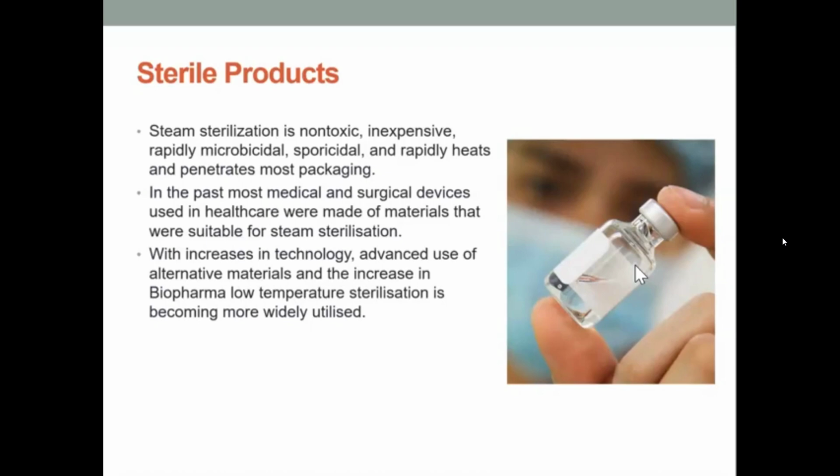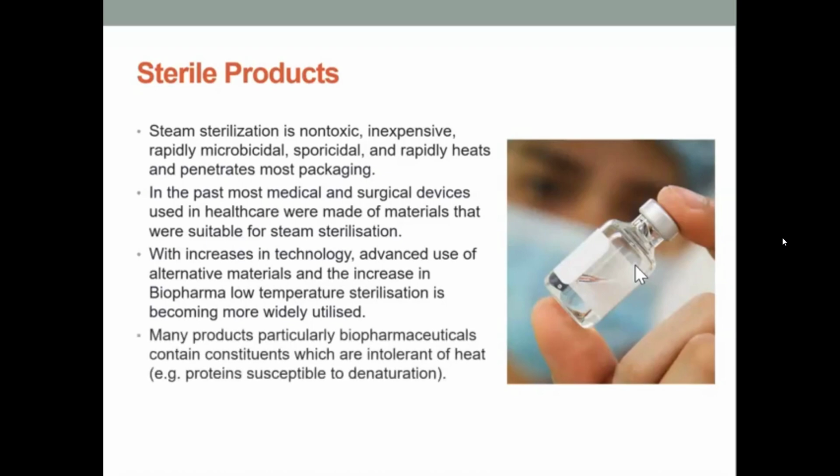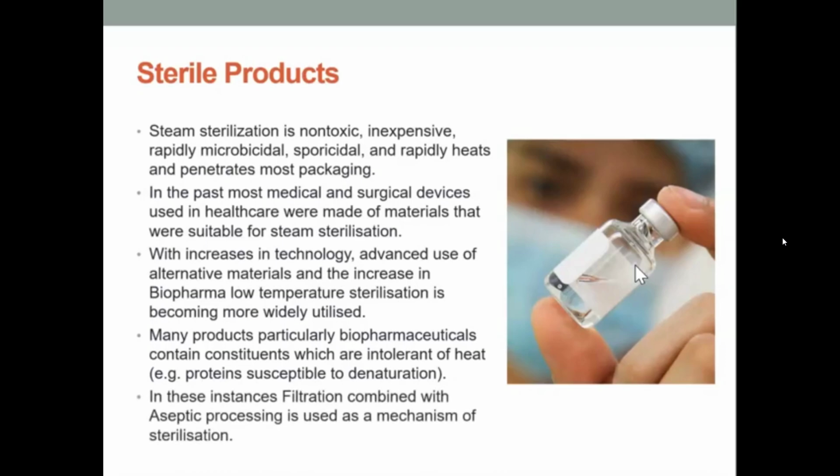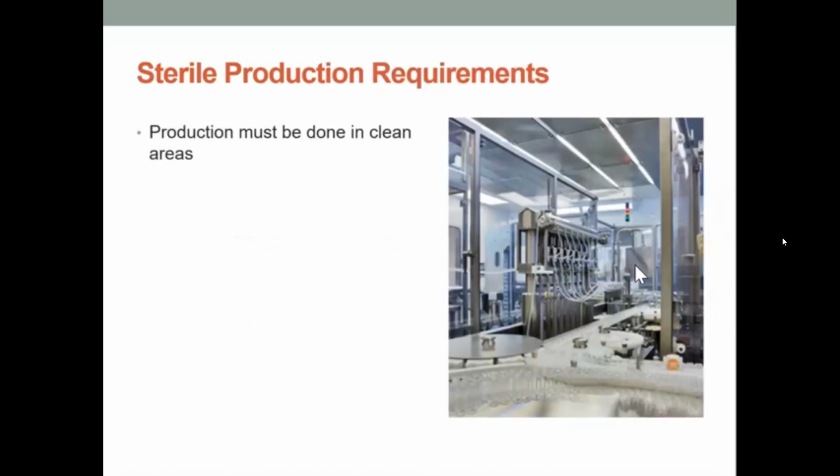becoming more widely utilized. Many products, particularly biopharmaceuticals, contain constituents which are intolerant of heat. For example, proteins are susceptible to denaturation with heat. In these instances, filtration combined with aseptic processing is used as a mechanism of sterilization.